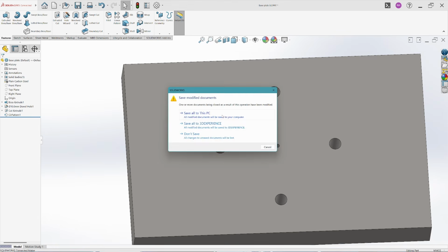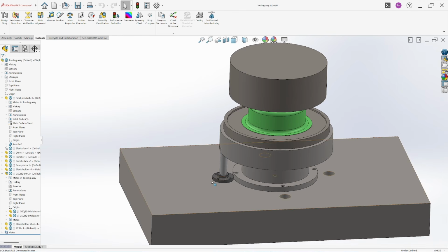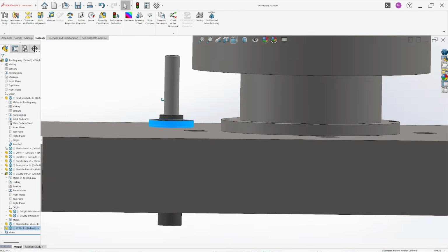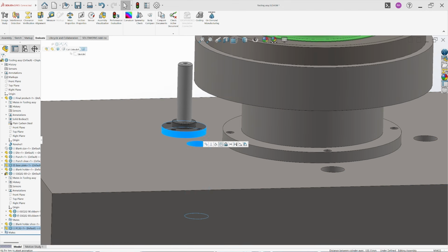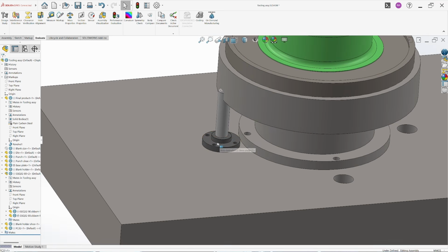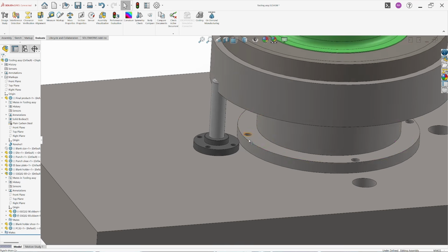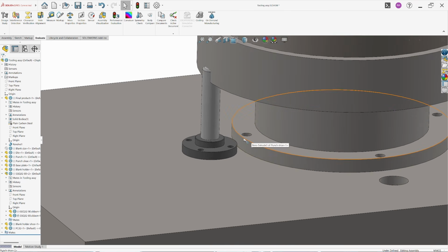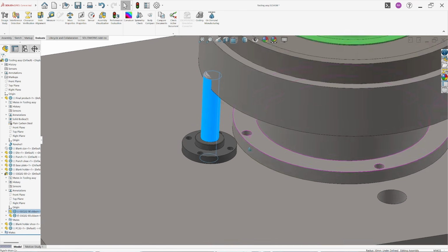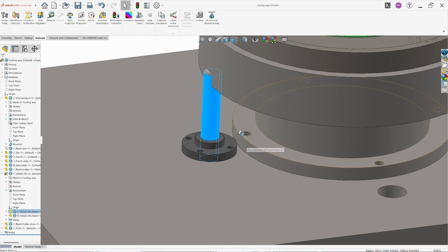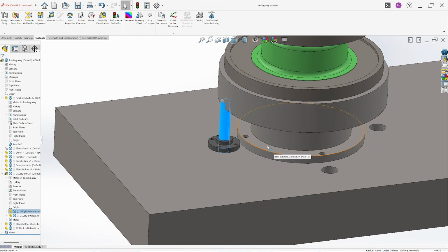Now get back to the assembly. Let's first try to mate this. Okay, now if you see, the gas spring is here, and also the mounting hole of the flange is here. So it will not be easy to put the Allen key or tighten the bolt. So what we can do is rotate the orientation of the flange, something like this. So we will have enough space for everything, for the gas spring, also for mounting of this flange.